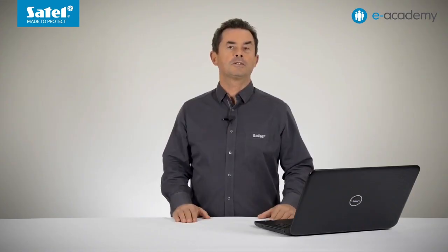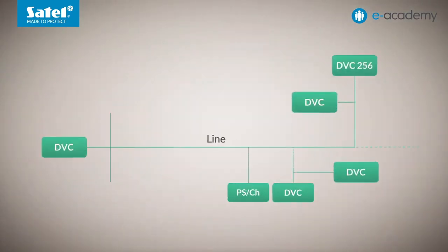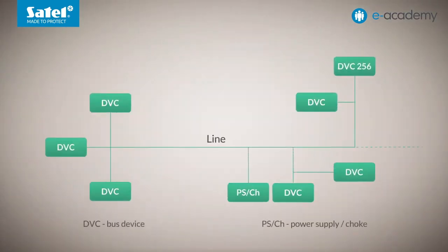Okay, I will now turn to a brief description of the KNX TP system topology. The basic unit of a KNX installation is the line. Up to 256 devices, i.e. sensors and actuators, and a minimum of one power supply can be installed in such one line. Within a single line, for example, a tree topology can be built, with branches at arbitrary points. This saves on cabling compared to a star system. It should be added that a ring structure is not used in KNX installations.